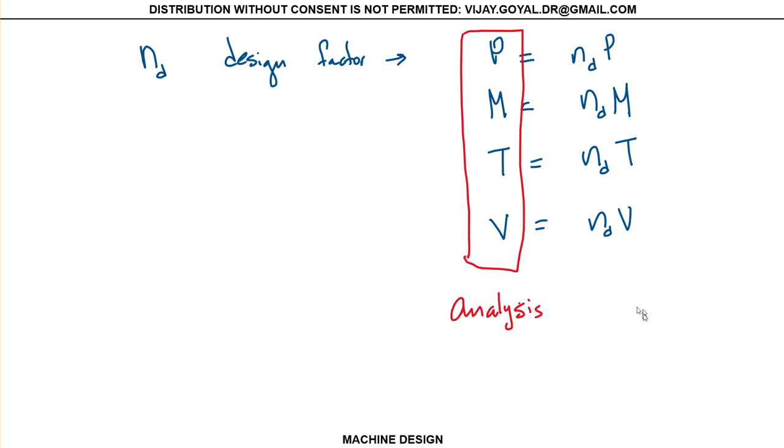So typically, design factors, as I mentioned to you, in many problems, a standard design factor can be 1.1 to 1.2. So that's kind of standard. Just add that to the problem, that's what we do. Now, if you don't have anything given, just put 1.1, or in many cases, with a very good justification, you can take this equal to 1. There has to be a good justification.